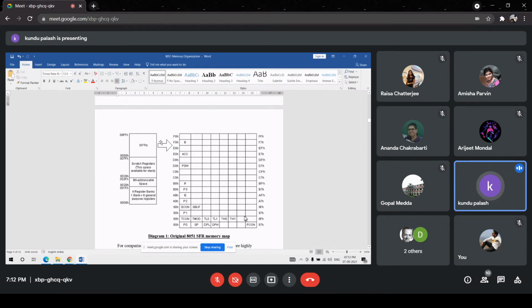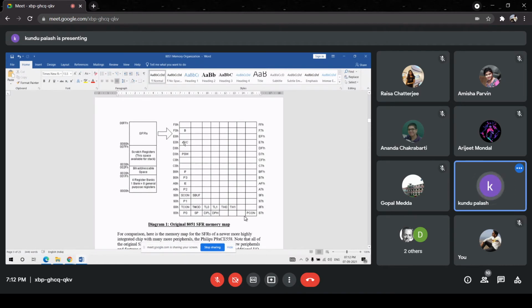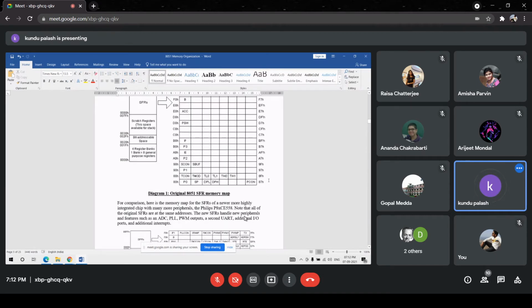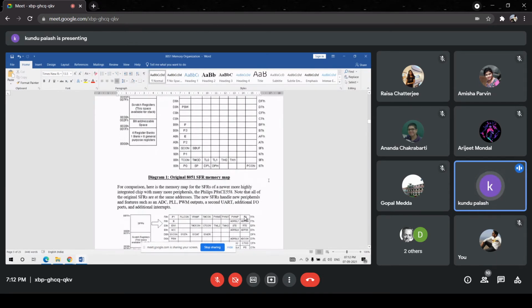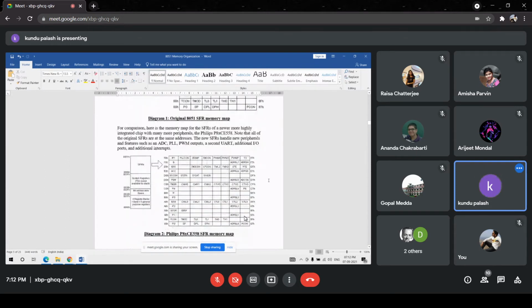So programming the internal peripherals means putting a bit stream in these absolute locations. But the user need not know these absolute addresses; by using symbols with the proper MCS51 compiler or assembler, using the proper directive in a statement, this can be programmed or filled in automatically. So this is the significance of the special function registers.